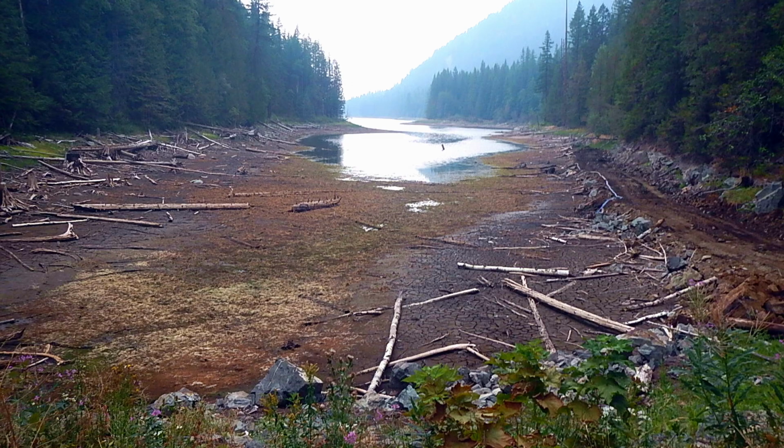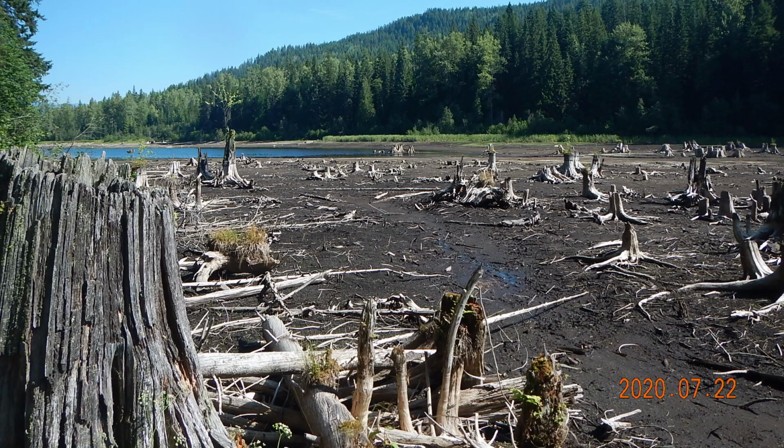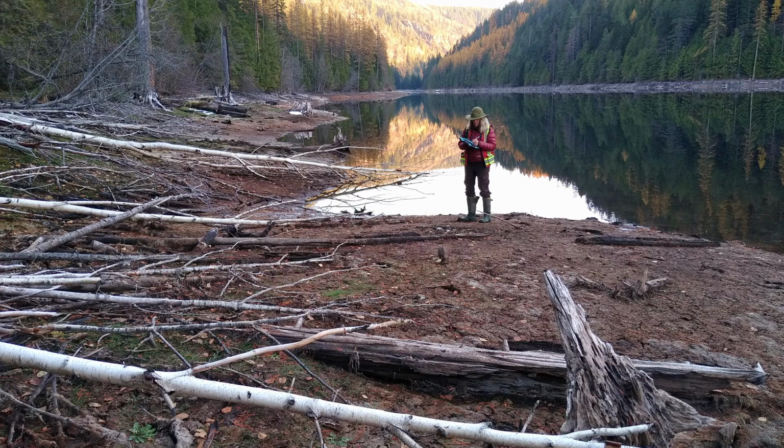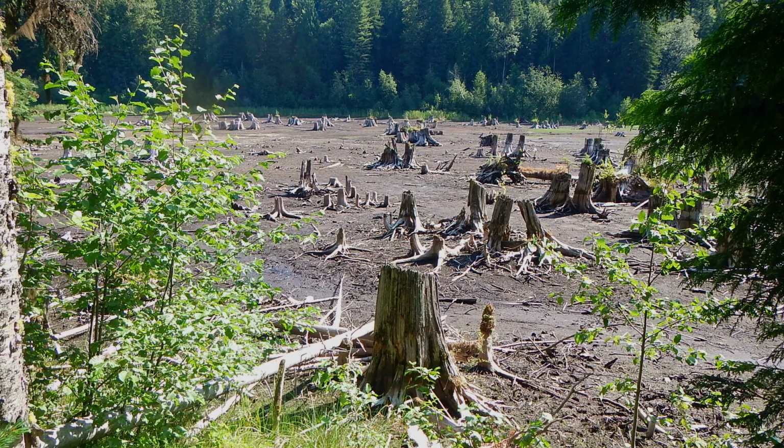This was important because of the high cost and the effort associated with pumping water around a dam while it's being removed. We worked to identify the historic elevation of the valley before the dam was built by taking elevation readings where the stumps of trees that had been inundated for years were now exposed near the inside base of the dam. The presence of tree stumps in the drained bay that was adjacent to the dam showed us that the soil had not been removed from the lake basin to build the dam.